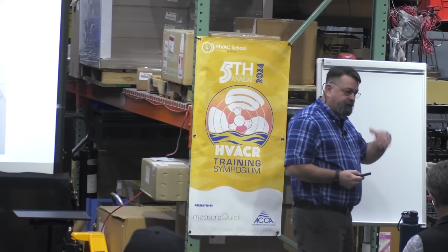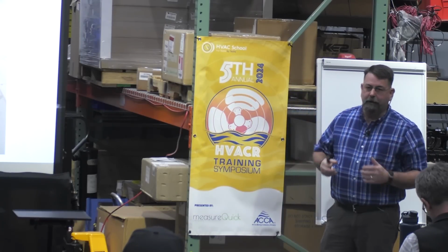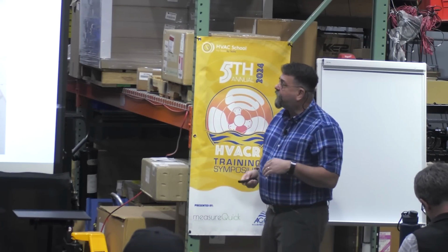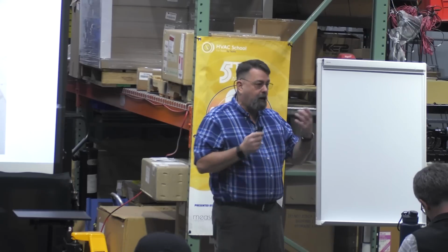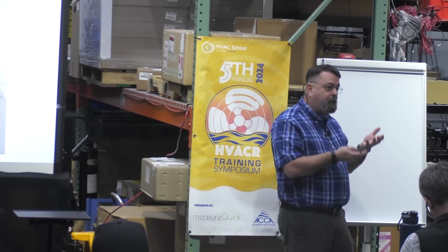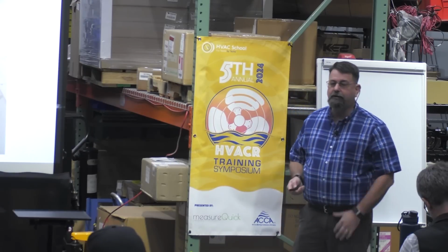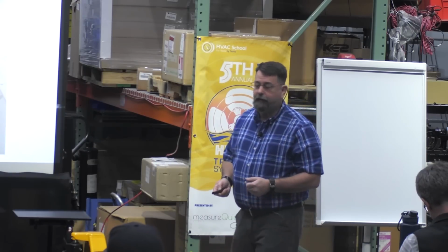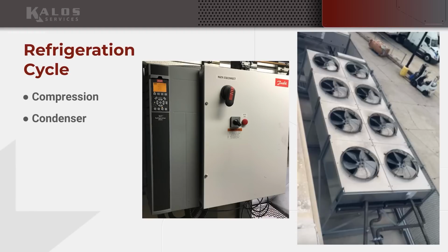Okay, so when temperature drops, I just watch my discharge pressure, and as that discharge pressure falls, I'm going to start shutting off fans to keep it up. Right, I got to maintain that pressure differential across that expansion valve. So I'm going to do that through staging my fans off. That is the old school way of doing this, and it's the most common, right?